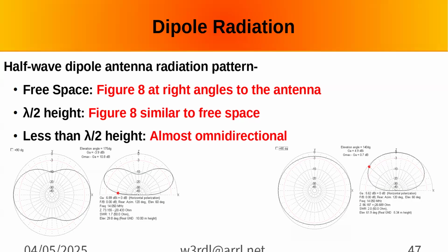I would think that close it would be ground wave. I would think the first 30 miles would be ground wave, and then anything between 30 miles and your first hop would probably be NVIS. I don't know, it could be either. Just like sometimes you can't tell whether you got long path or short path.